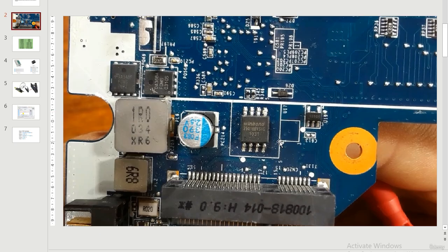Pin number 1, as you can see here, is marked with this dot. Pin number 4 is always connected to the ground, and pin number 8 is always connected to VCC, or 3.3 volts. As for the BIOS sizes, I taught you that in order to know the size, you should read the reference above the body of the BIOS.